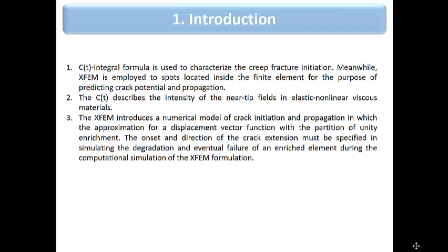For the introduction, the C(t) integral is used to characterize creep fracture initiation. Meanwhile, XFEM is employed to locate the crack inside the finite element for the purpose of predicting crack potential and propagation. So this study focuses on creep crack growth, where creep initiation is represented by the C(t) integral, and XFEM is used to represent crack propagation and growth. Second, C(t) describes the intensity of the near-tip field in an elastic non-linear viscous material.